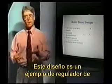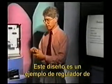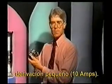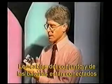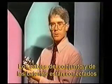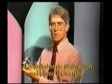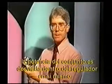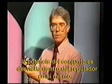An example of a small type of shunt regulator might be this type of design, a 10 amp shunting type of regulator. The array and battery wires are connected to the shunt regulator, and so might be the loads as well. When the battery reaches too high of a voltage, the power of the array is shunted within the regulator itself.